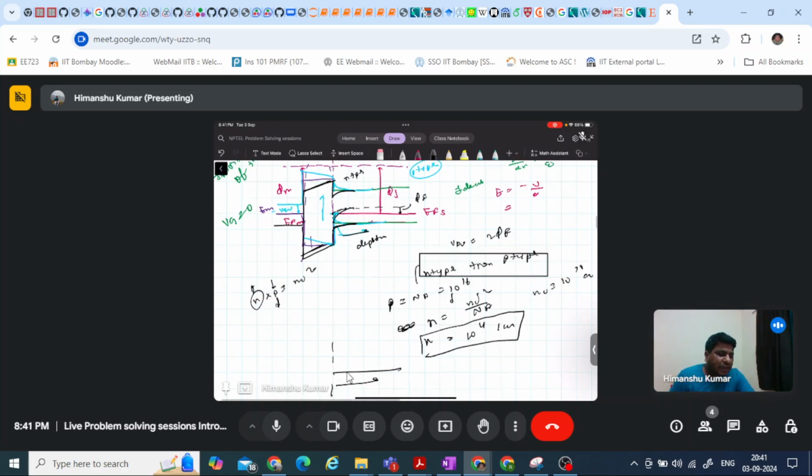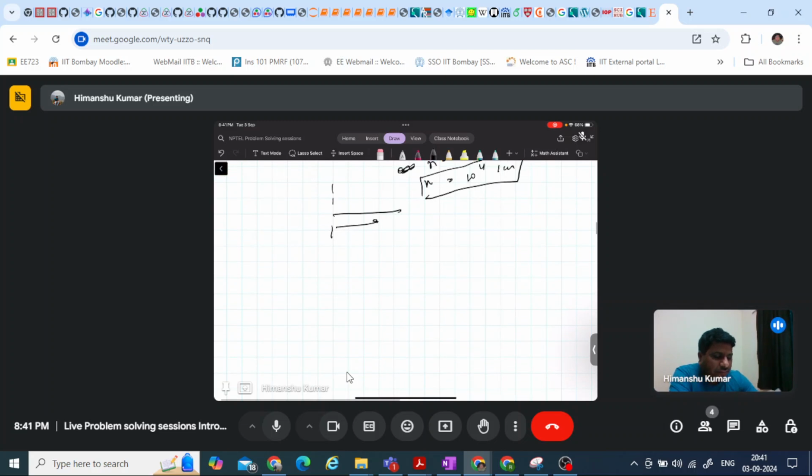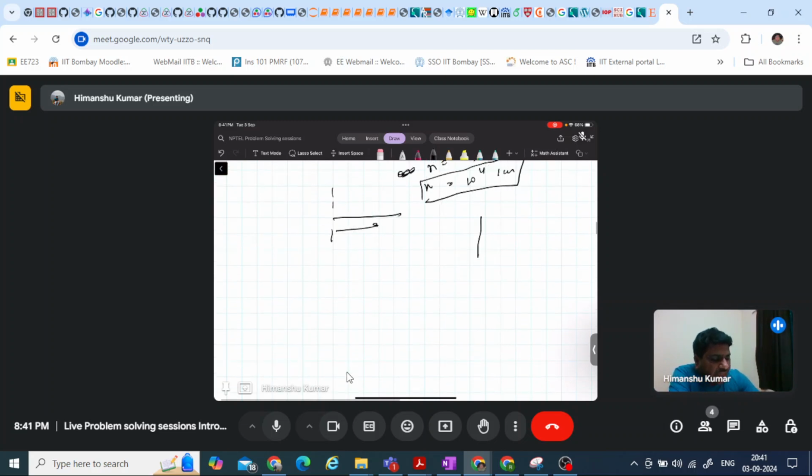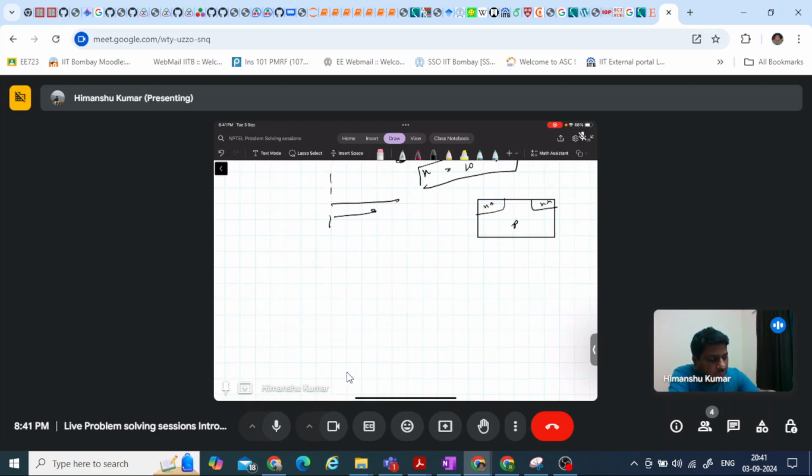Particularly in the MOSFET case, if you draw the band diagram, this is n plus, n plus and this p plus. In a MOSFET there is the metal oxide semiconductor here, but this side a p-n junction is also there.